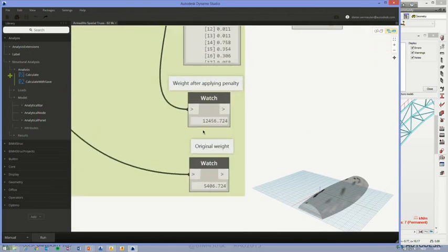So there are 129 bars in it, so I get 129 truss results, which is the total stress for self-weight, permanent and variable in one time. So you could also add some specific safety factors on it, but I didn't do that in this case. I just sum everything together and then that's it. Here is the weight. So the weight at this moment is 5,406 kilogram for that specific truss. So if I change the value manually, then this value will change also.